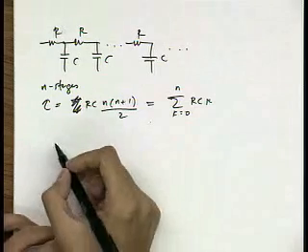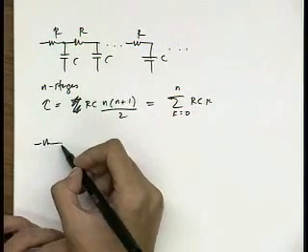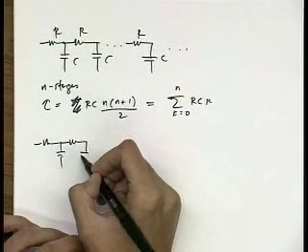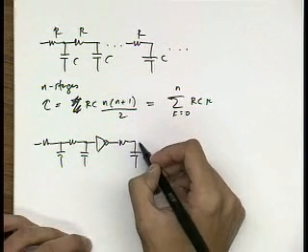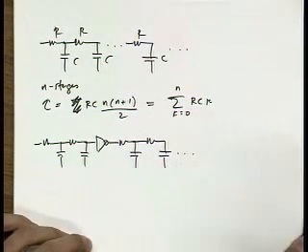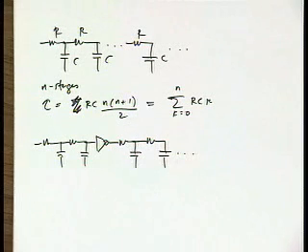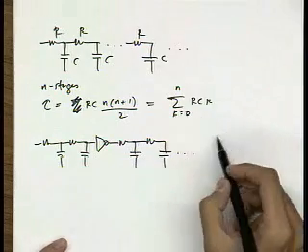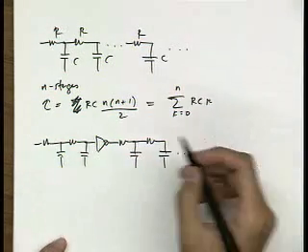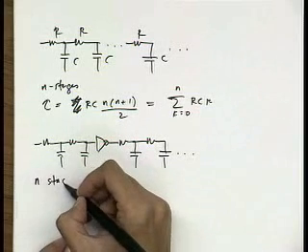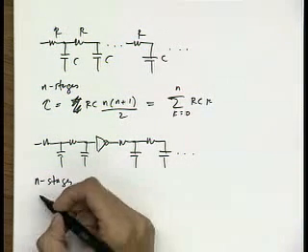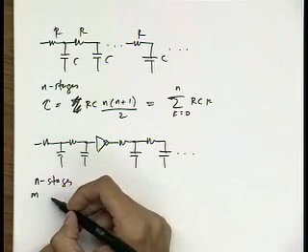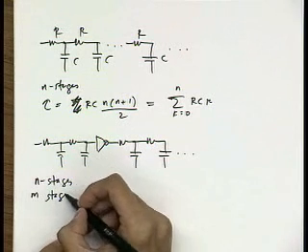So obviously it's proportional to n squared. So the idea is if we try to break this up into segments, and then we drive each segment with an inverter or a buffer, then what will be their new delay? Let's say you still have n stages, but now you have m stages per segment.